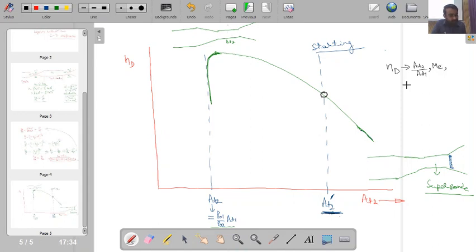Third important function is flow angle, because when you put some object in the test section, that will deflect the flow. So when the flow comes to the diffuser section, it may come at a certain angle. Now we are assuming that in our test section, whatever object we place does not make any deflection in the flow, because we are considering quasi one dimensional flow. But whenever we place such an object, that will also make some deflection, so we will have some flow angle. And how much is the length of this second throat is also an important parameter in controlling the efficiency of the diffuser.